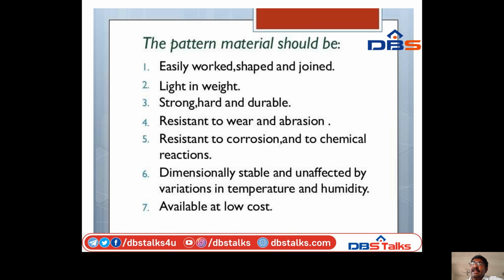So the pattern material should be easily worked, shaped and joined. It should be light in weight, strong, hard and durable. It should be resistant to wear and absorption, and resistant to corrosion and chemical reactions. It should be dimensionally stable and unaffected by variations in temperature and humidity. And it should be available at low cost.